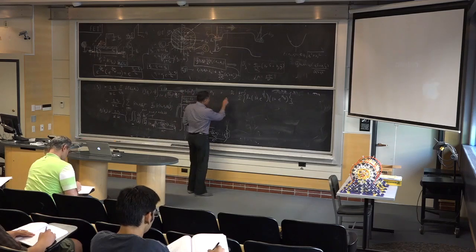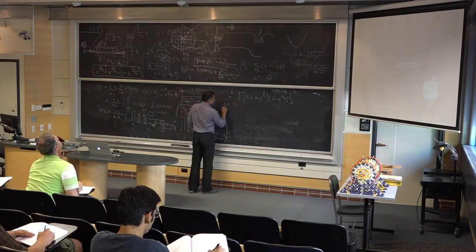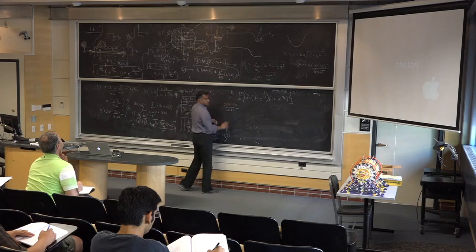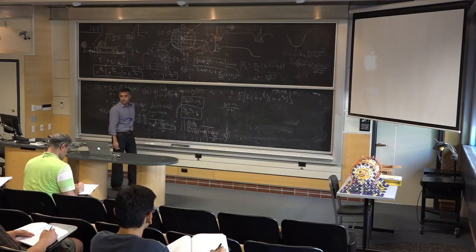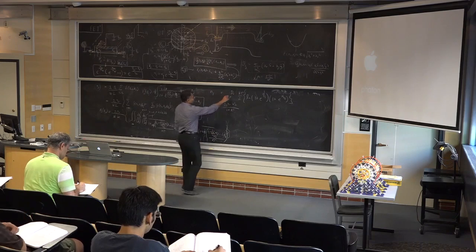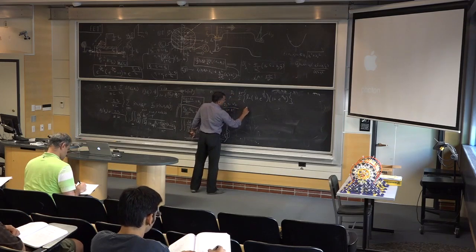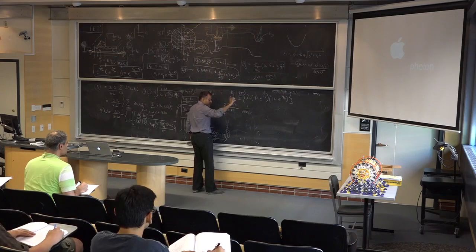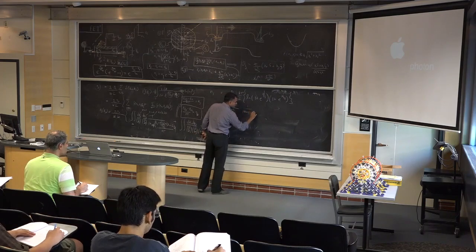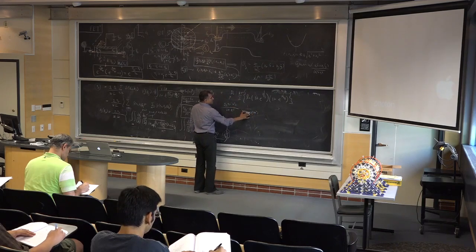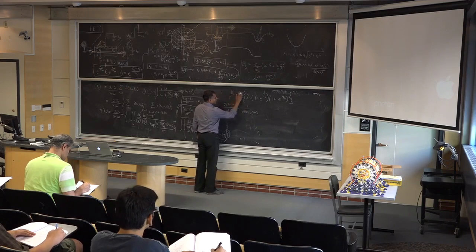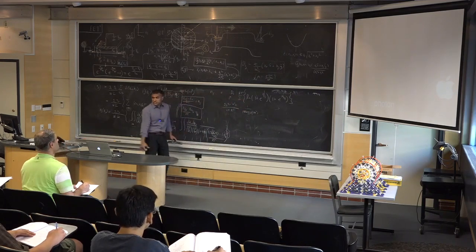Right? What is D naught? I think we have written that it is spin degeneracy, valley degeneracy, effective mass over 2 pi h bar squared. That's D naught. So all that stuff gets just clubbed into the front, right? And density of states in 2 dimensions always has units of 1 over energy. Density of states is how many states per unit energy. So there's energy, and in 2 dimensions, it's per area, or centimeter square. So D naught is 1 over energy centimeter square. kT is energy, so you get 1 over centimeter square. That's the sheet density of carriers.